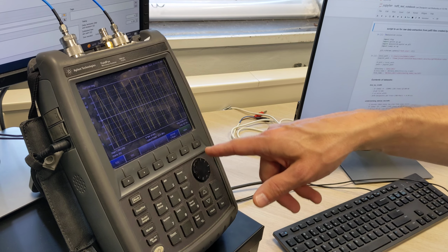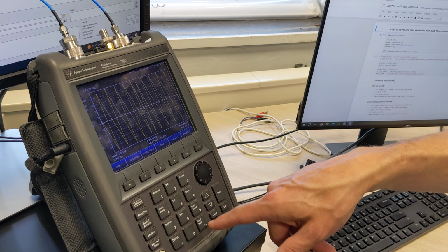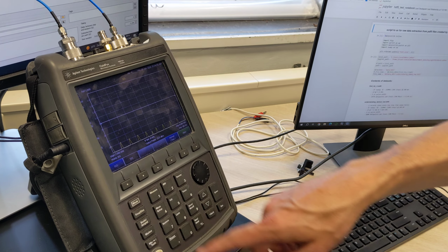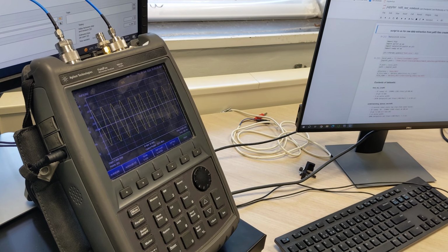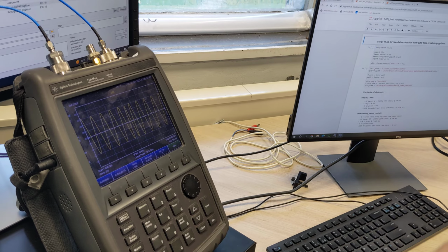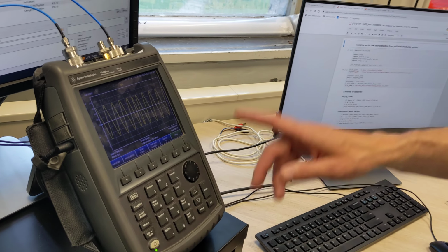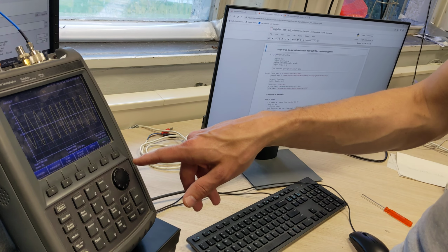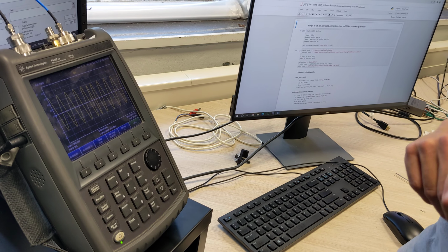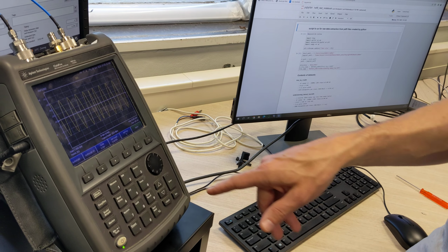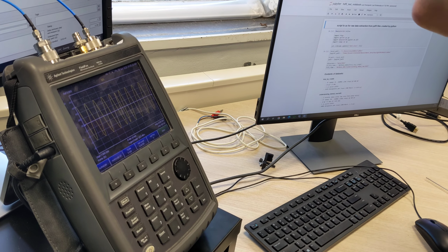So that's why if I just say I want to look at the real and imaginary part, I'm just going to see madness. I'm going to see wibbly oscillations, and I don't know where the cavity is. What we need to do, if you want the real and imaginary part on the display of the network analyzer to look like they should according to the formulas, is correct what's called the electrical length.